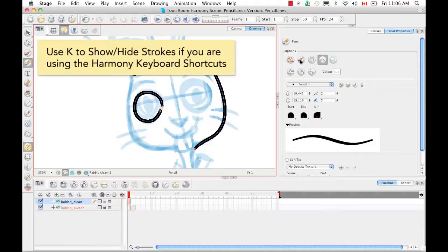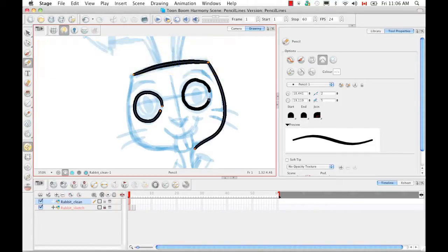But with the auto close gap, as you approach the tip of a circle, it actually finishes the circle for you. It'll join the vector line. So even if there is stylistically a gap, or it might just be a mistake, for example, the contour line will get finished for you. And obviously it depends how close the two endpoints are, because these two apparently were not close enough to have a finishing line, but this one was.